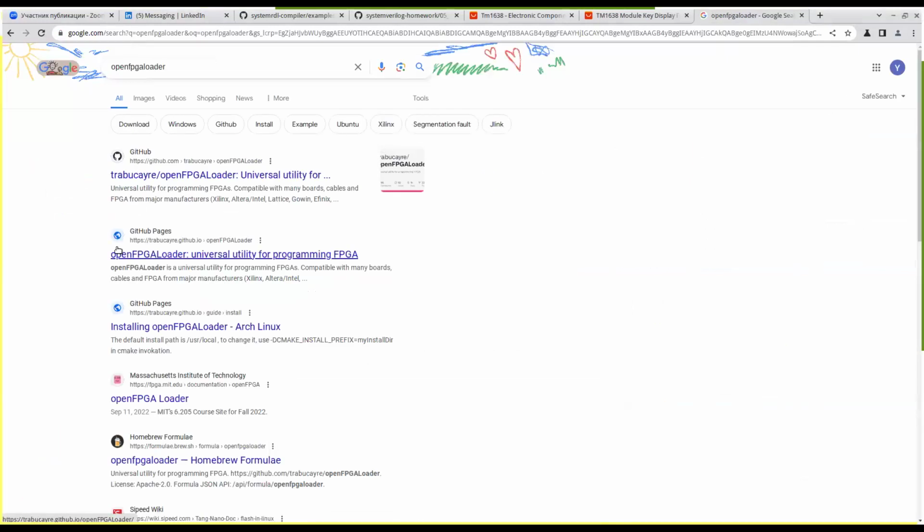One problem with Gowin is that the Gowin toolchain works both under Windows and Linux, but unfortunately the Gowin EDA tool for Linux does not work properly with FPGA boards. So one of the participants, Alexander Ryabov, and Victor Vizovtsev, who was working with him, suggested using OpenFPGALoader.